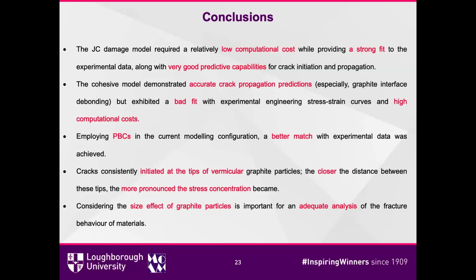And the PBC will give a better match with the experiment when we use it, and the crack consistently initiates at the tip of the graphite. And the closer the distance between those tips, the more pronounced the stress concentration became. And the last is, when we consider the size effect of the graphite particle, it's very important for the adequate analysis of the fracture behaviors of the materials.